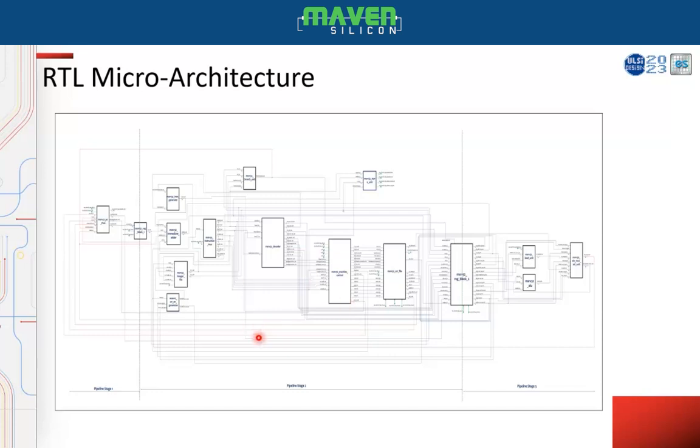So basically the instruction is 32-bit wide, which contains various fields like opcode, operand 1 like RS1 register address, RS2 register address, or if it is I-type instruction, then the same 32-bit instruction will also contain immediate value instead of RS2 register addresses.